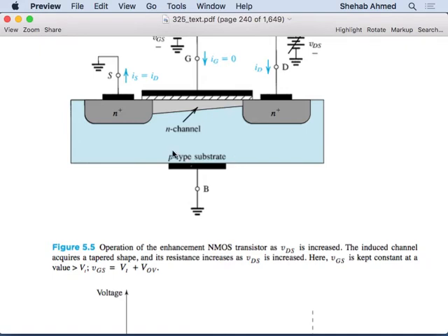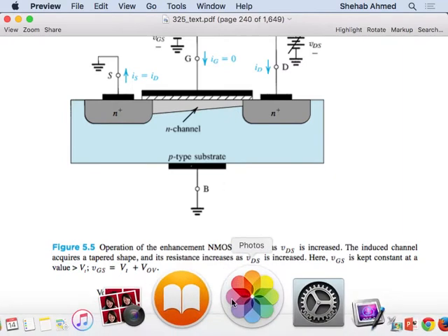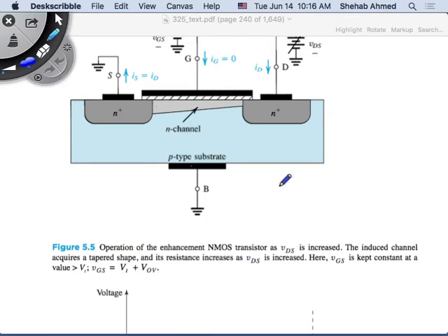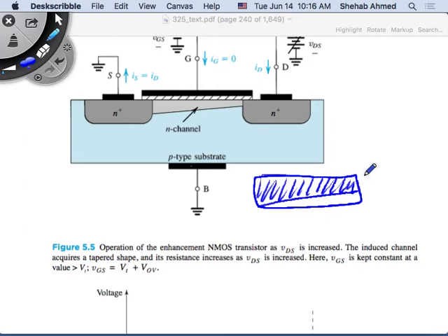So this change in area means, if I want to simplify my calculations, I will think, okay, what is the equivalent rectangular area? This is not a rectangle anymore, so it's difficult to calculate the area for this, right? But what is the equivalent area for the rectangle? This was my original rectangle. Now I lost thickness, so I look like this, right? But this area here is equivalent to having a rectangle like this. The rectangular areas are easy for me because with width and length of the channel, I can calculate the area that the electrons are flowing through, right?